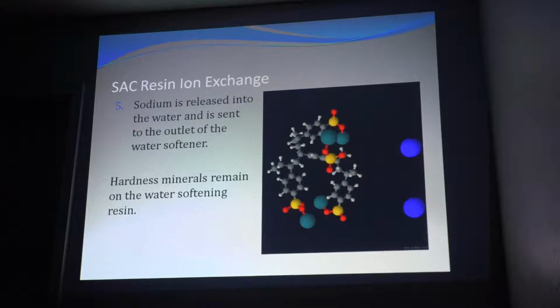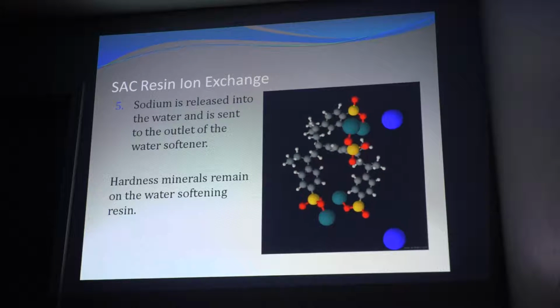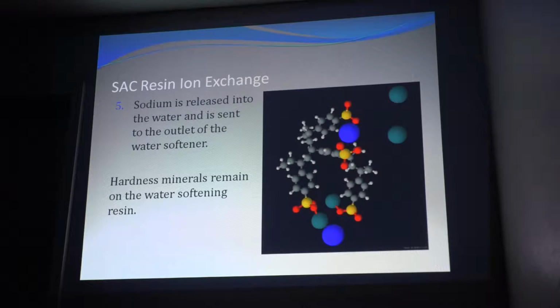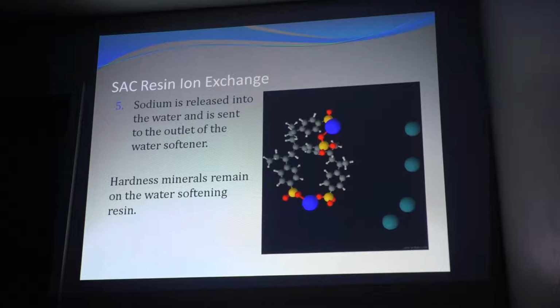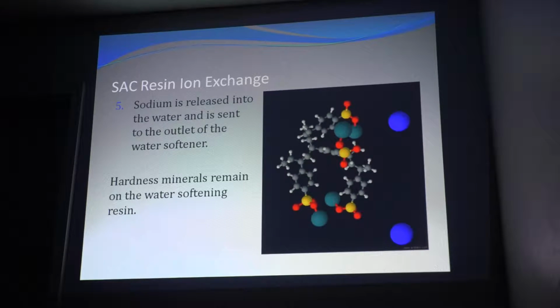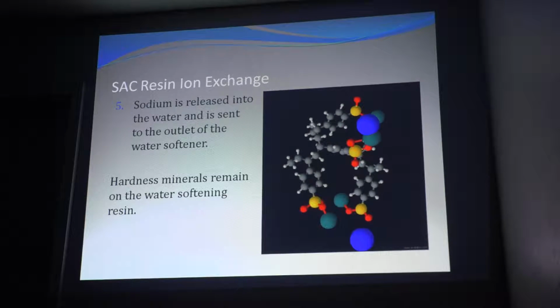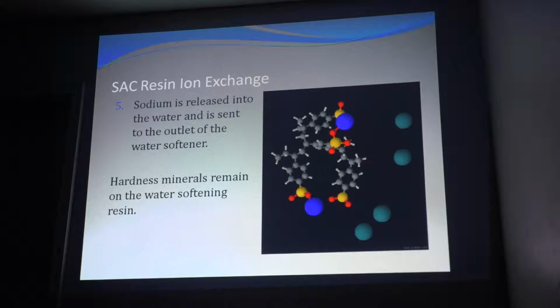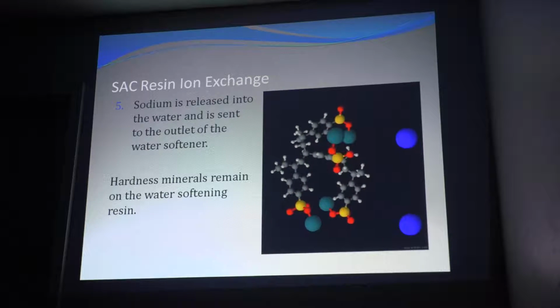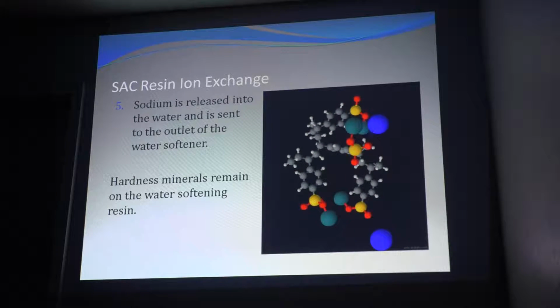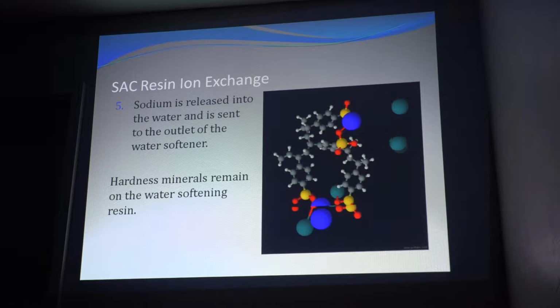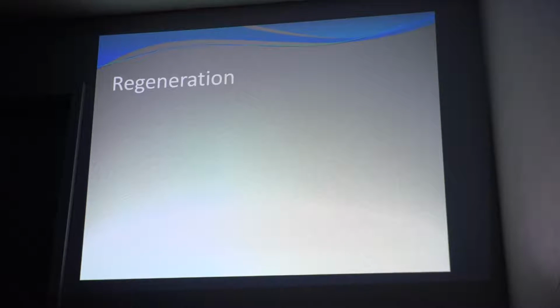Sodium is released into the water and is sent out to the outlet of the water softener. A lot of people say, well, gee, I shouldn't drink soft water because we're drinking salt water. Well, that's all relative to the amount of hardness that's in the raw water, and we'll get to that shortly.